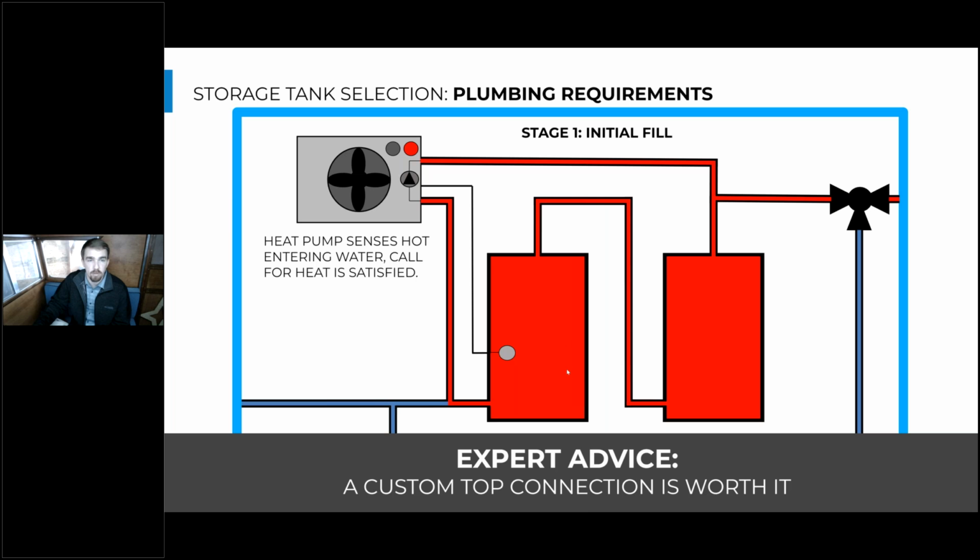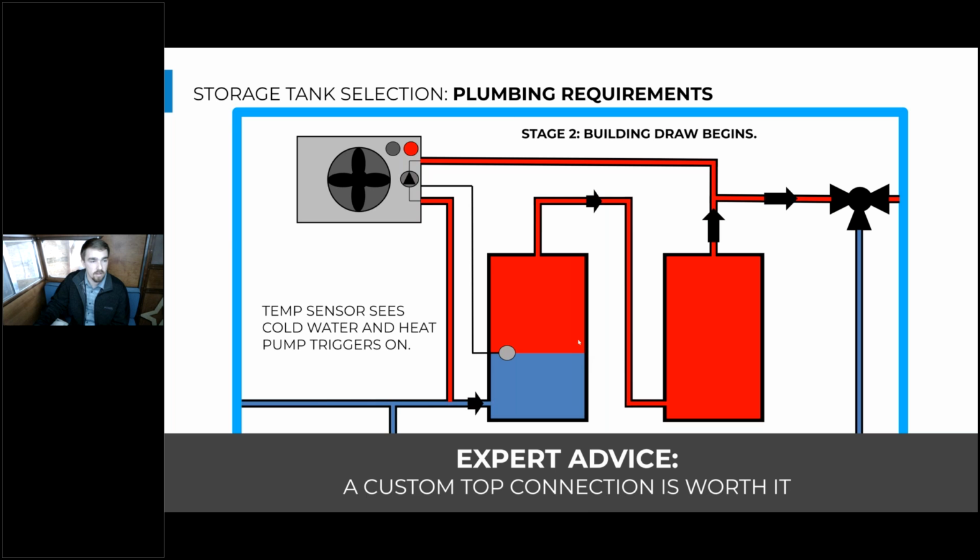And then after the heat pumps filled this system initially, we will have a hot water draw from the building, and then that cold water will make its way up into the bottom of this first tank in series. At this point, the heat pump hasn't turned on yet because this cold water hasn't made it to the heat pump sensor. So this sensor location is really important to think about in terms of how your control sequence will operate. We'll talk more about that later.